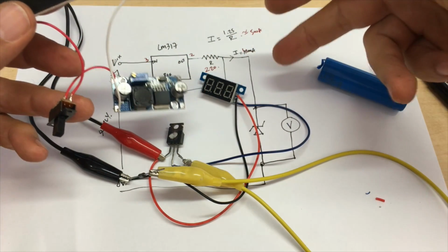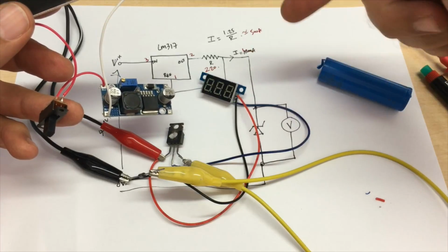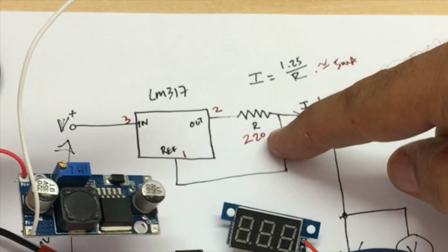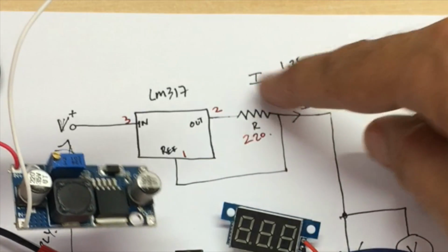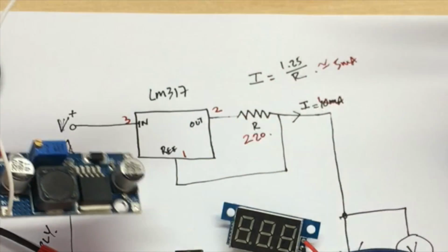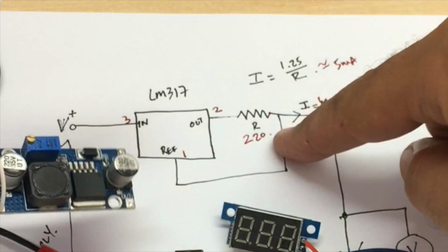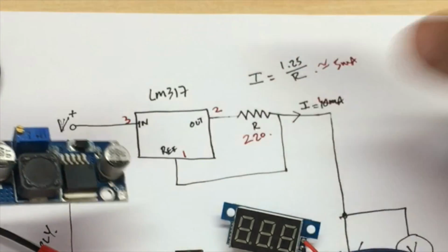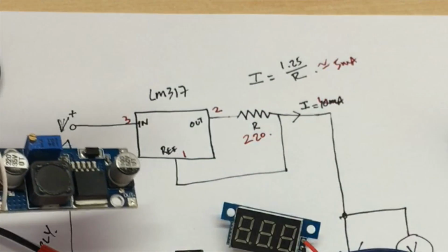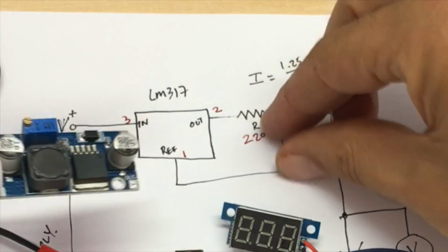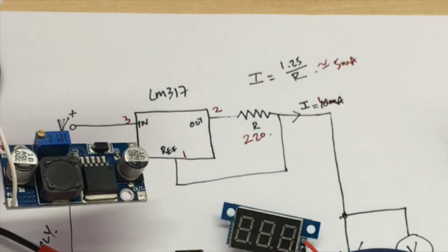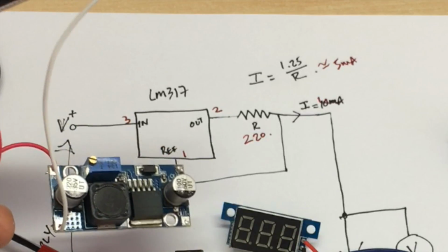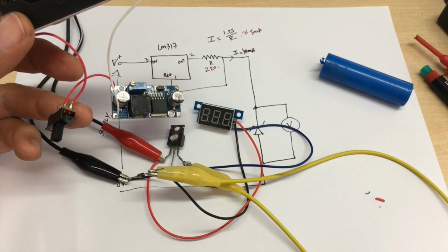The other thing I could possibly do, and I think I will do, is have a switch where I can switch in that resistor or switch in other resistors in parallel with that. So this is set for 5. So if I put another 220 ohm resistor, it'll give me 10. If I put in something else, I just got to work it out, it'll give me about 15 or 20 milliamps. So I can actually switch what range of test currents I want to use. But those are all things I'm just trying to decide on now. I'll give it some thought and see where we go.